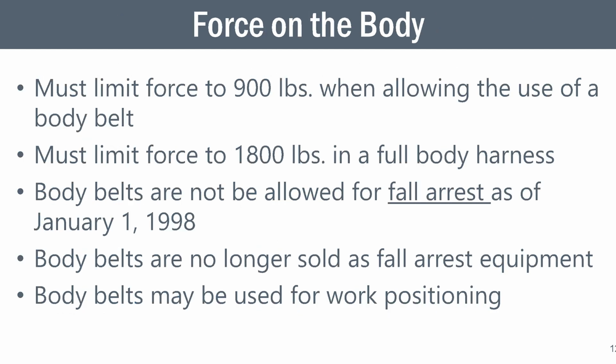Now, I mentioned the forces applied to the body. Back in 1988, I know it's a long time ago, but I want to bring it out, that's why people got away from safety belts for a fall arrest system, because the standard says the maximum force limit on the body can be 900 pounds.